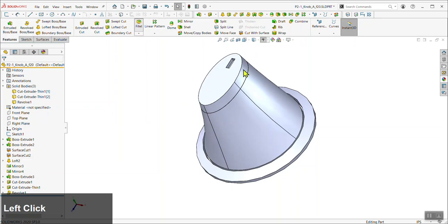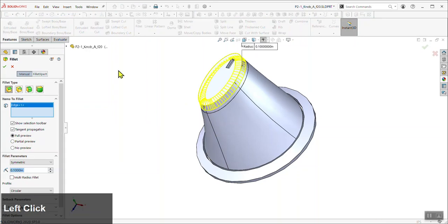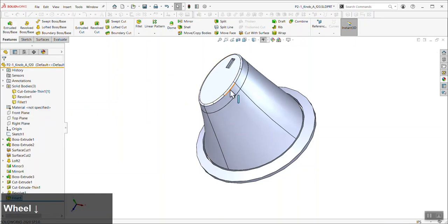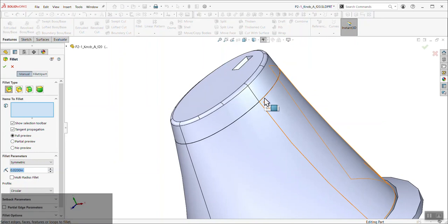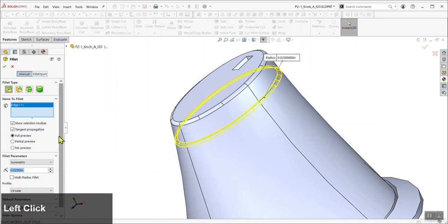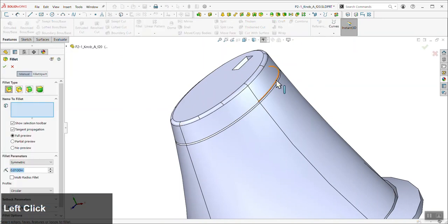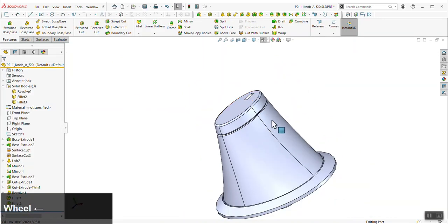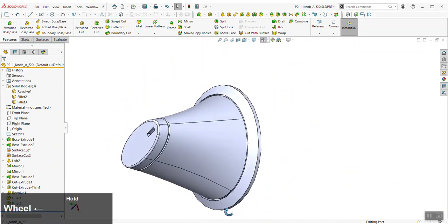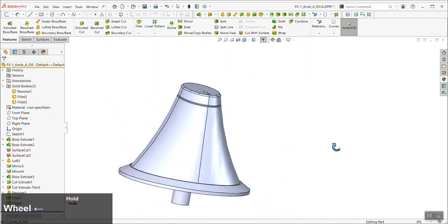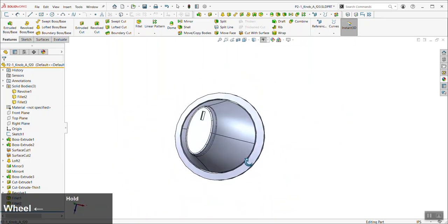The last thing to do would be to go in and add fillets. Again, if I'm matching my aesthetic, the fillets might be on the smaller side. You want to add your part line fillet between the cap. So again, 0.02, 0.01 will be somewhat realistic. I guess I went to 0.01 because I already had a smaller fillet on top, and I just wanted that part line fillet to look a bit smaller. So there you have it. A lofted knob for the appliance.